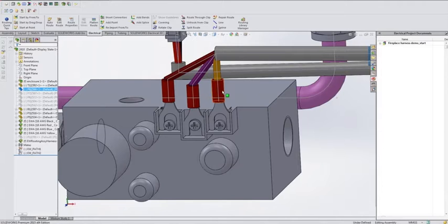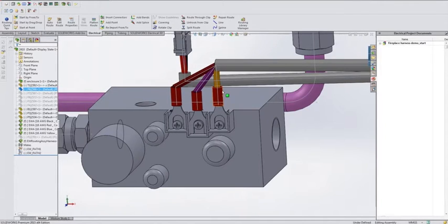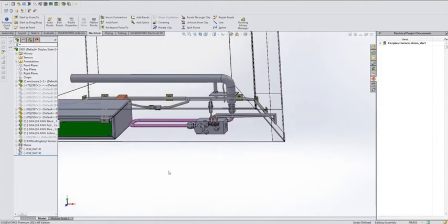And then afterwards, what they would do is associate and say, okay, well, that's what the electrical engineer called P6. I can go ahead and right-click and associate that with P6. So once again, it's less of a serial process and more of a parallel process. Once we all have those components set up, we'll go ahead and route up our harnesses in this case. And then if we want to go one step further, flatten it out and also create our project drawing.